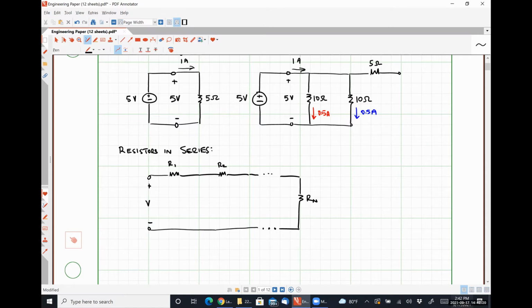If that voltage V is being provided by a voltage source, so I'm just going to dot this guy in over here. Really, all we need to have is a fixed voltage, but I'm going to do that by having a voltage source V. I have a single loop circuit where all of the elements are connected in series, and so they should all have the same current flowing through them, right?